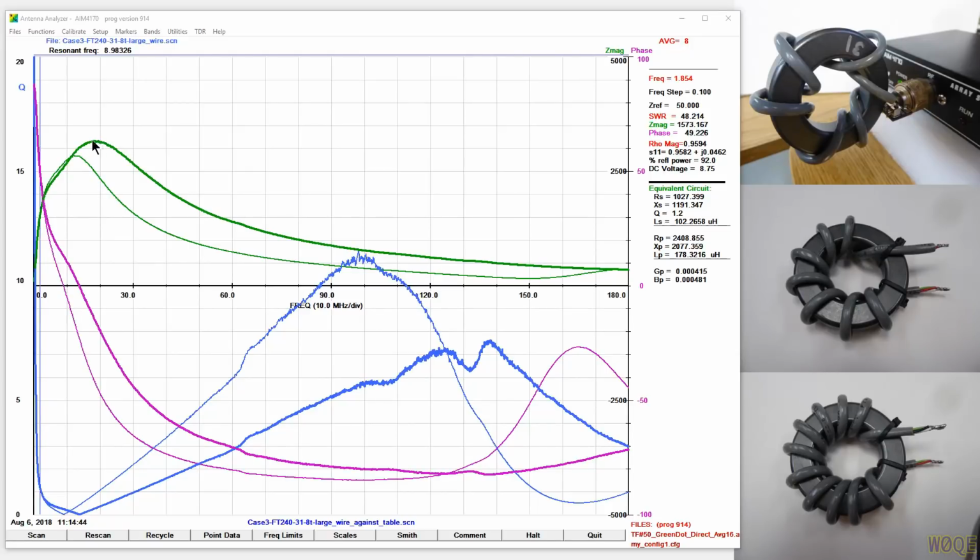impedance. Anytime you try to get these impedances very, very high, it's extremely difficult to do that if the core ends up touching anything at all. I mean, you think about what 3,000 ohms of impedance or 5,000 ohms of impedance at 30 megahertz is about 1 picofarad is equivalent to what this thing represents, 1 picofarad of capacitance. And being near just about anything reduces its effectiveness. So that's something to be concerned about.